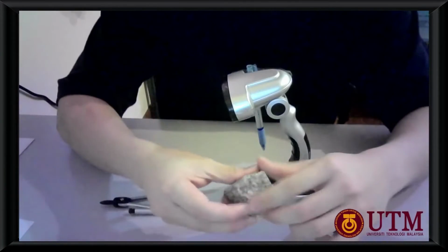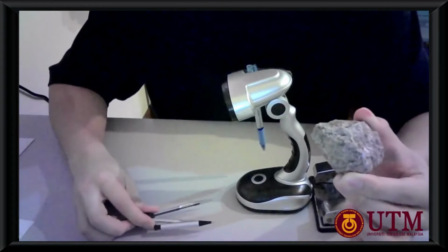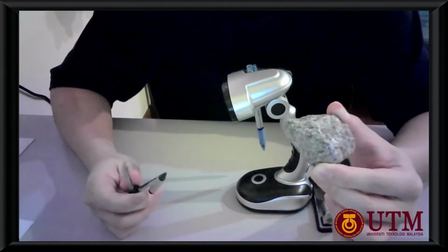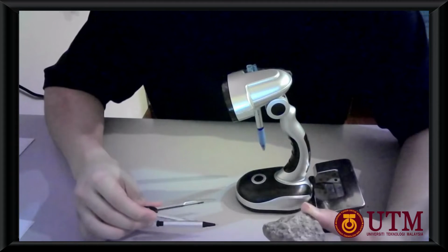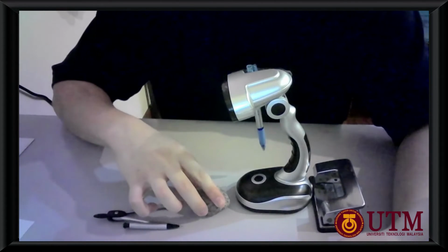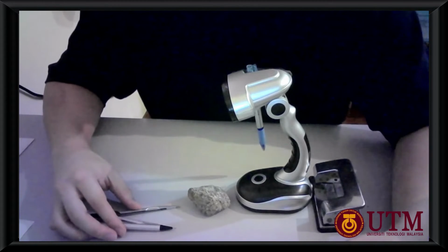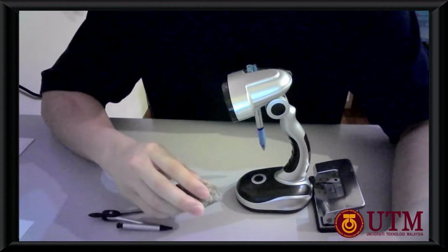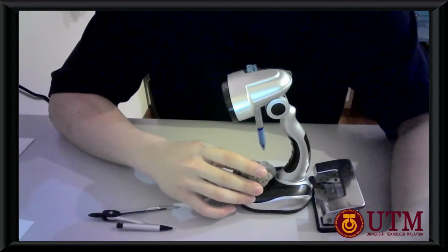First, we measured the upper width and also the lower width of this rock specimen with this vernier caliper, which is perpendicular to the loading direction, and call them W1 and W2. So that we can use this information to calculate the average width by adding W1 and W2 and then dividing by 2. The rock specimen is placed horizontally between the upper platen and also the lower platen.